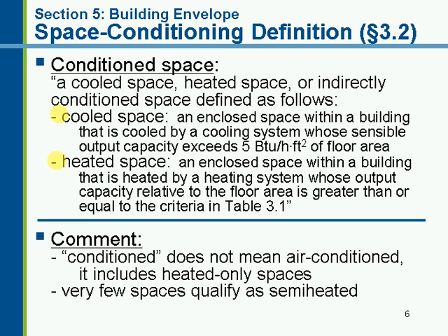Office space is more in the range of 15. So what people were calling semi-heated spaces actually had a peak heating load 5 times as much as the fully insulated and fully heated spaces, even though the semi-heated spaces were only being heated to 50 and the fully heated spaces were being heated to 70. So again, relatively few are going to fall into that semi-heated space category.